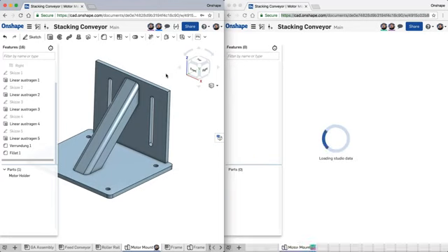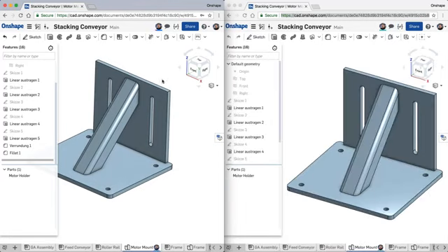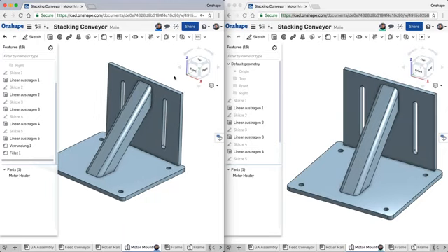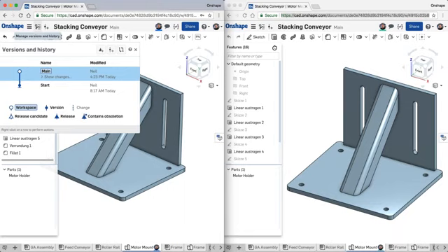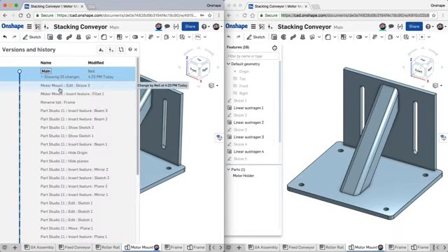All right, so when we're working in the same document, and when we make changes, what you'll see is that there is no save button along here. Even if we look in here, there is no save button, because every time you do something in Onshape, it is recorded. So we'll see that we edited sketch 3, we inserted a feature, renamed a tab, and this essentially gives you unlimited undo redo. I can go backwards and forwards through this version history and see exactly how a design looked weeks, months, years in the past.